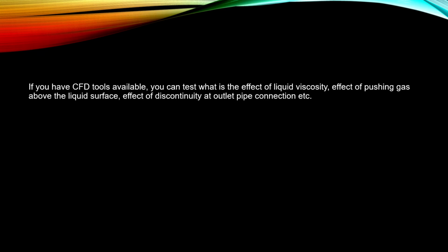If you have a CFD tools like Fluent or OpenFOAM, you can test what is the effect of viscosity. Calculate first with water and change the liquid to high viscosity oil. Look at what is the difference in time to empty the tank.